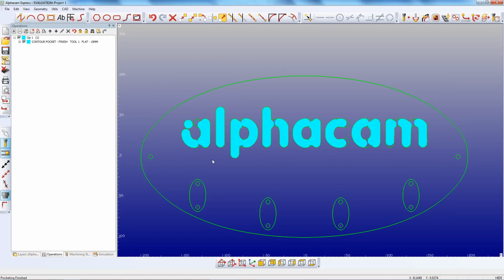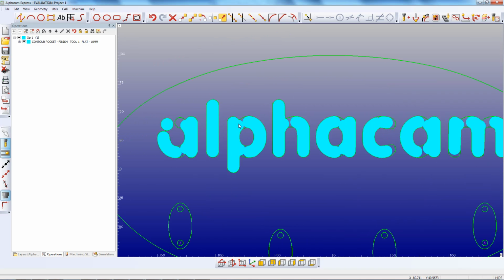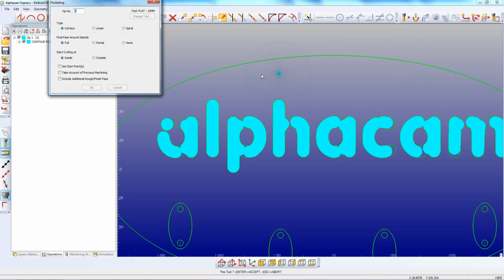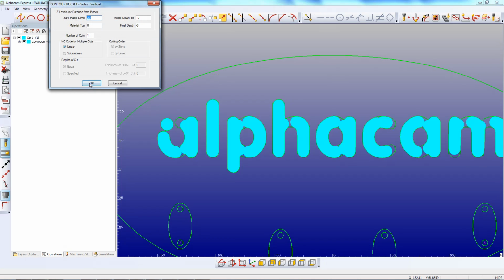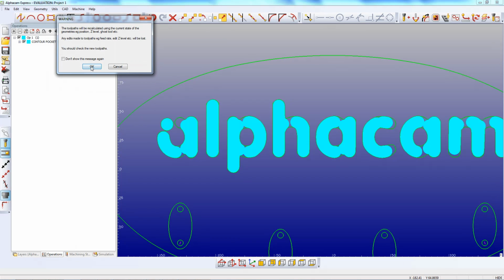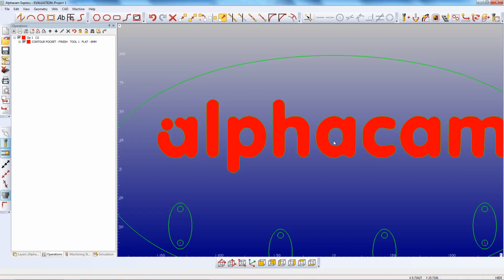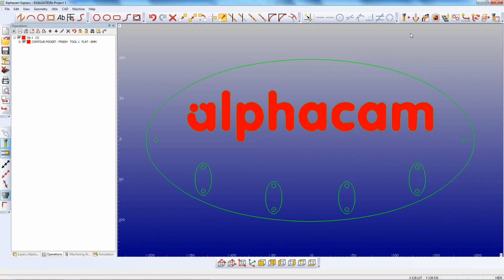It's geometry. I've got the material cut switched on there, and I can see that it's missing certain areas, so we can come back into here and we'll edit that tool and we'll change that to the 6mm, and we'll just update these. We'll reselect that 6mm tool for the rest of the operations because I don't have a tool change on this machine, just a simple machine.